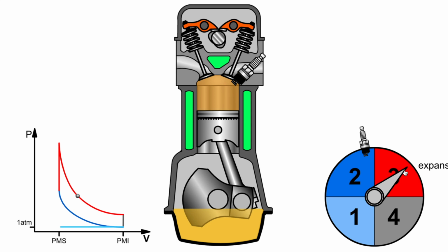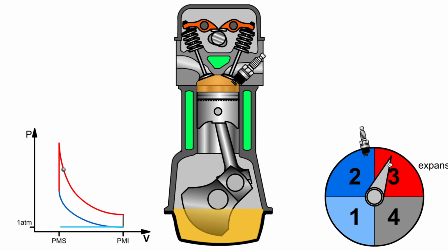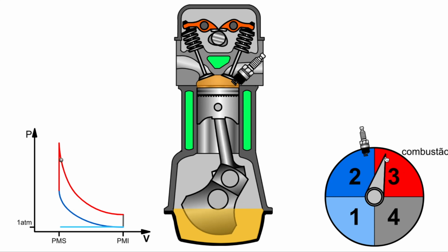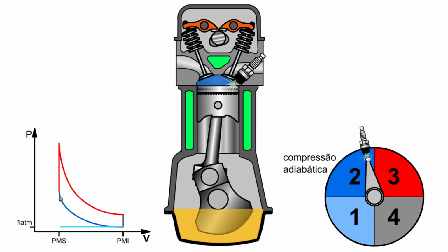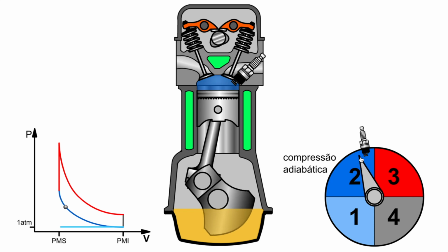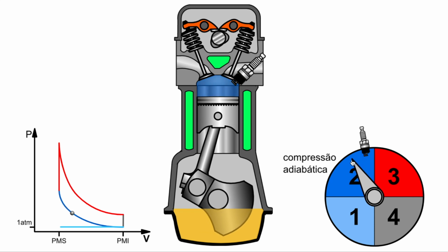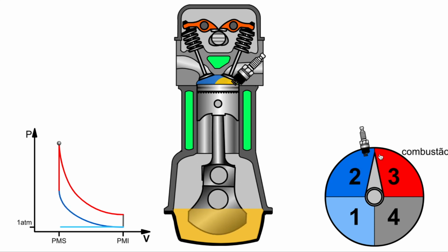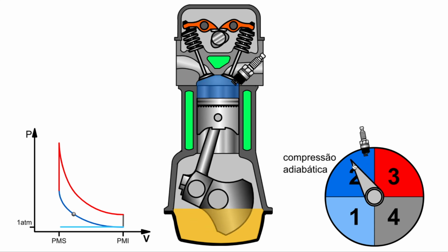So that means you'll lose a lot of your kinetic energy as heat rather than power. That's why one of the things to check for if your Model A is overheating is your spark might be coming too late. So to get the peak pressure to occur just after TDC, you have to fire the spark plug before TDC. And as your RPMs increase and the piston starts to rotate faster and faster, you have to advance the spark earlier and earlier to get that peak to come at the same point, right?